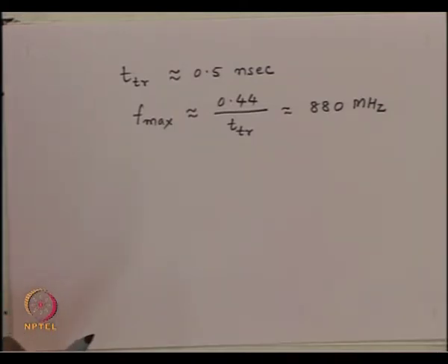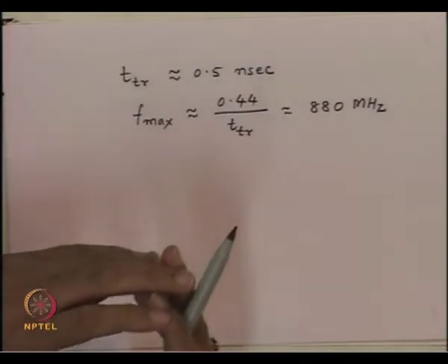The frequency response of the photodetector is one of the important components, because that is going to decide what kind of data can be received by this junction. Later on we will see in fact that this is the response which restricts the higher data transmission on the optical communication link. We will see that there will be fibers which have a very low dispersion, and lasers which can be switched at a very high rate. So, finally, the limitation will come from the photodetector for realizing high data rates on the optical communication link.